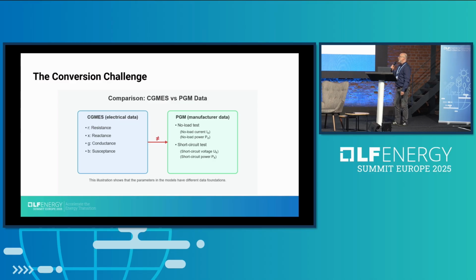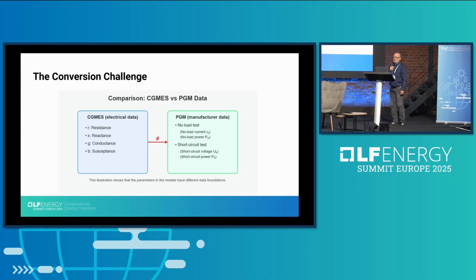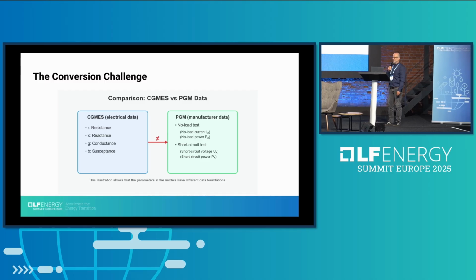This was our task. We had an internal study to import CGMES data into PGM. But the first approach doesn't work because CGMES takes only electrical values, whereas PGM needs the manufacturer data from no-load tests and short-circuit tests. So we can't import CGMES data in a direct manner. We had to work around it.